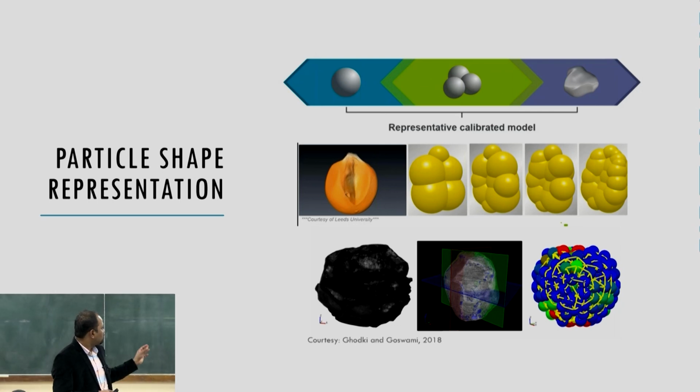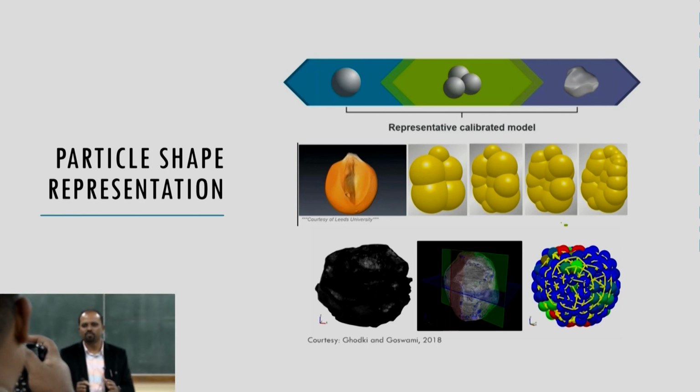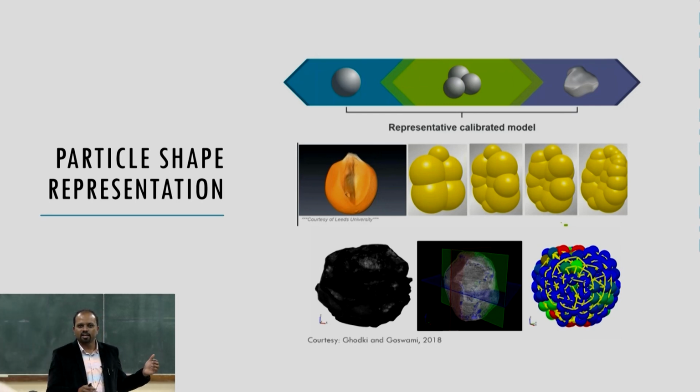And on the bottom you can see a black pepper seed. I was interested in the grinding part, and I chose the bonded particle model and defined certain stiffness, and I chose a certain number of particles based on the force deformation characteristic in the UTM, universal testing machine. So, here are 522 particles, and again on the back side of that we did X-ray imaging.